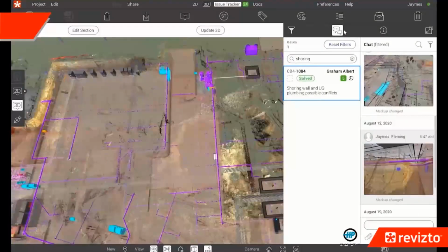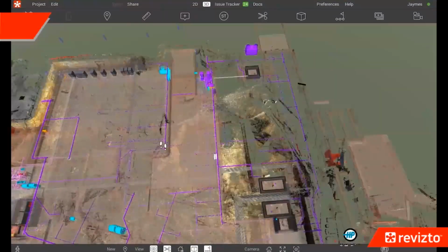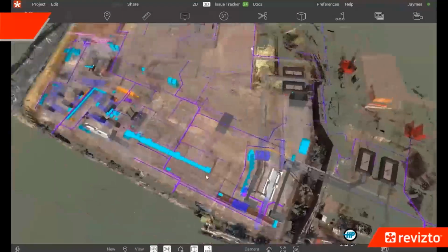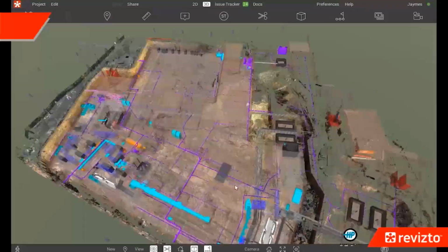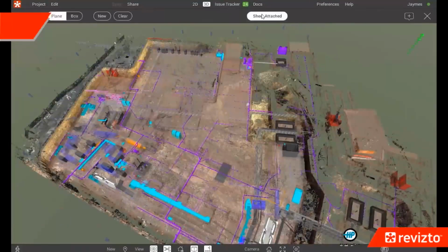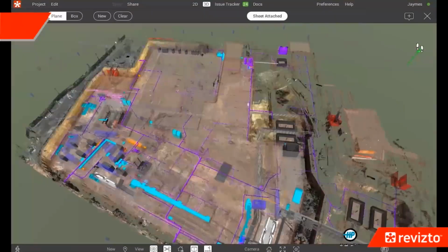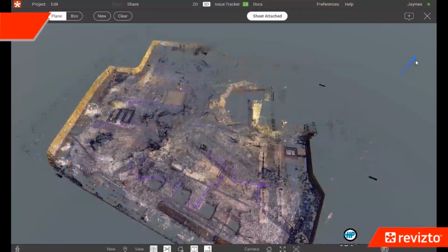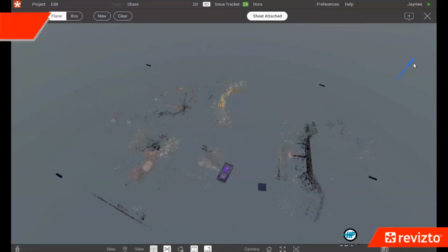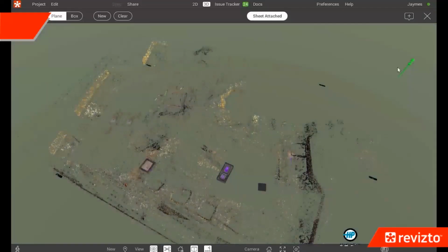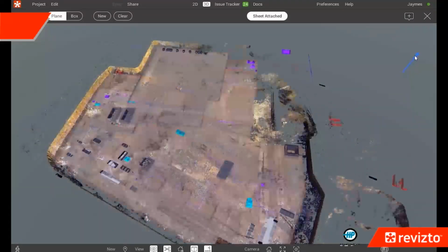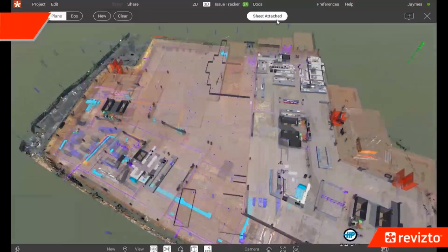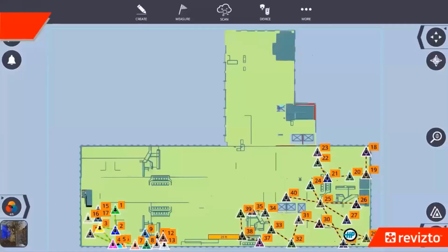The scan information was useful for those particular areas that we identified, but all of that data is also available for anything else you might want to look at as far as areas of excavation. In particular on this project, they were putting down like a rat slab and some riprap, and we were hoping it would all be lower than our intended routing for our underground systems. But using that scan, we could identify areas where they weren't low enough.